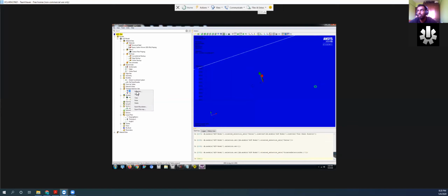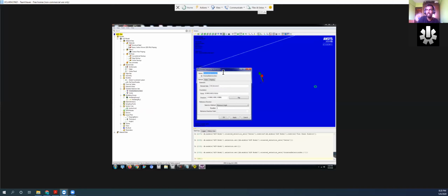And then I'm going to edit this. So if you want to edit an oriented selection set, you can right click on it and then click properties, and then you can rename it. So in this case, I'm going to rename this oriented selection set that I created earlier. Also, if you just want one piece, for example a flat panel, usually you just make it one ply. You're not going to split it up into different geometries. Then you don't need to come up with a named selection set, and automatically ANSYS will create this thing called an all elements set, which you can just use to give everything a uniform one ply. That's only if you're using one piece of carbon fiber for each ply.